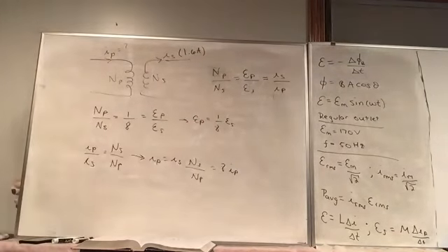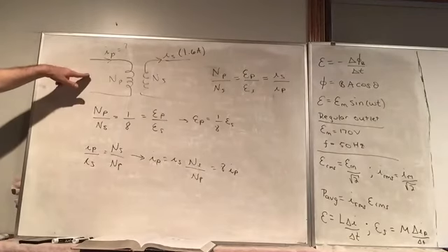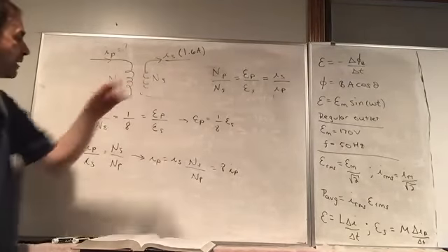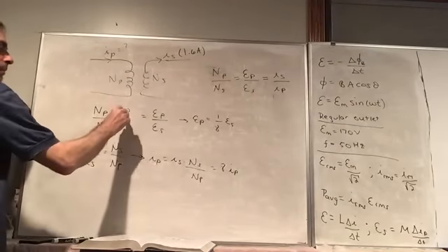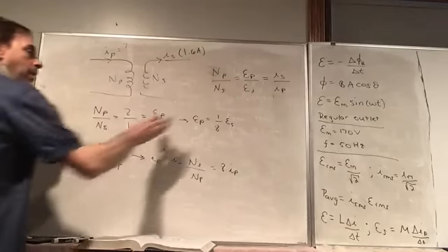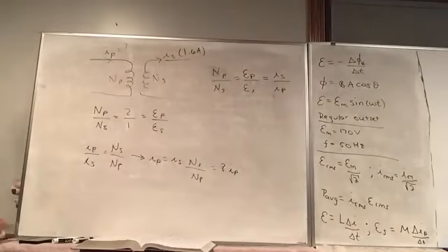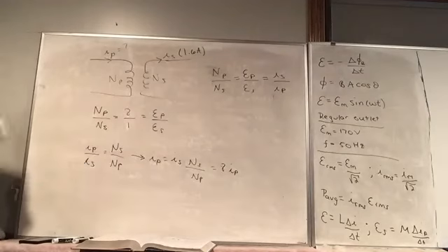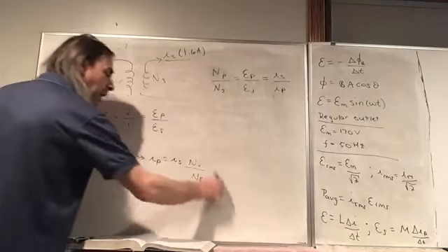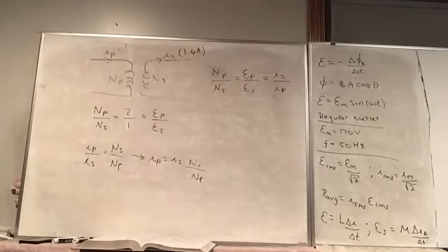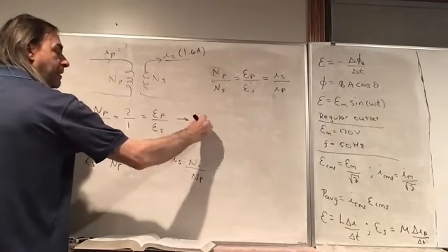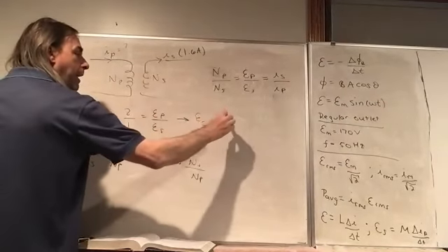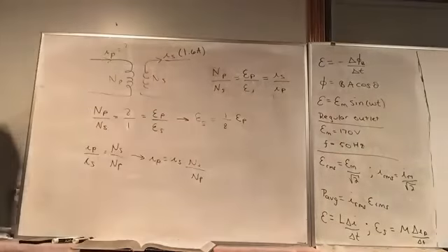Yeah, the EMF for a step down transformer, the primary should be at a higher voltage than the secondary. So I should have written this as 8/1. And now we have the EMF in the secondary coil would be 1/8 what's in the primary coil. So sorry about that. But yeah, this one makes sense. The EMF in the secondary coil is 1/8 what's in the primary coil.